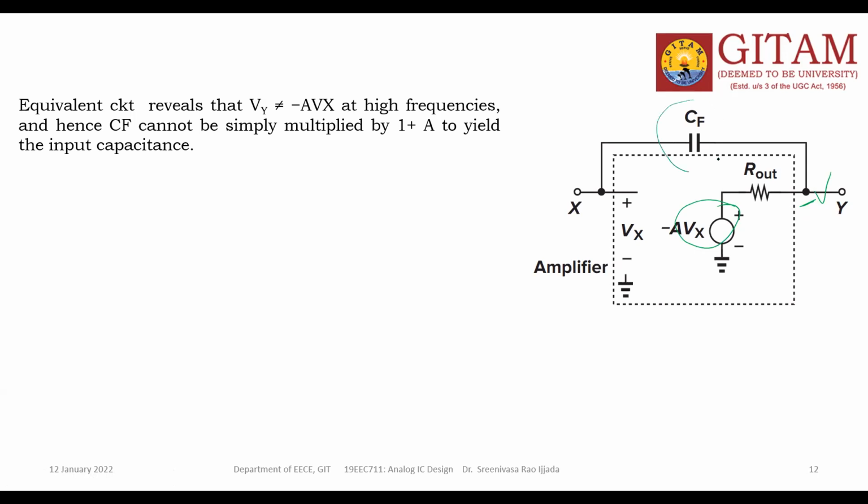If you take CF, it exists between this side and this side. So this is the floating impedance Z. I can replace this CF with Z. I can split this and connect like this, and you can remove this one. Then what is the value of this one and Z2? We should calculate as per the previous analysis.